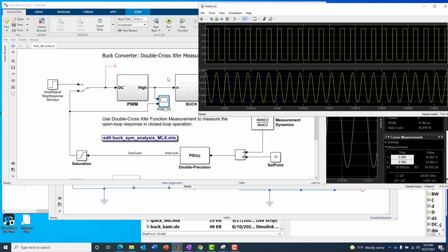The buck converter, most of the dynamics are in, let's say, the 0 to 10 kilohertz range for this particular buck converter, and the switching frequency is usually an order of magnitude or so greater than the buck converter's own bandwidth, or at least the dynamics of interest here. So this frequency here is not going to be of any use anyway, and even if it were, it would only be one frequency.